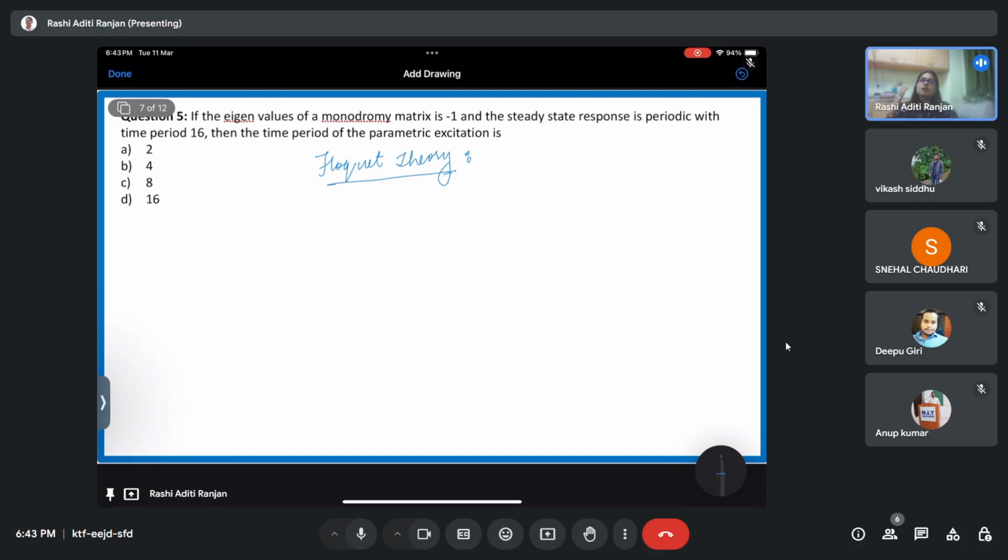Because for a force excited system, we find the equilibrium point and then we find out about the stability. But for a parametrically excited system, what should I do? Even if I try to find out the Jacobian, can I find it? Because earlier, when we were finding out the Jacobian for the case of a force excited system, we had to differentiate with respect to the state space coordinate x dot. Here, I have a parameter that is multiplied with the state space coordinate, which is dependent on time, correct? So even if I try to find out Jacobian, my Jacobian is essentially time dependent.